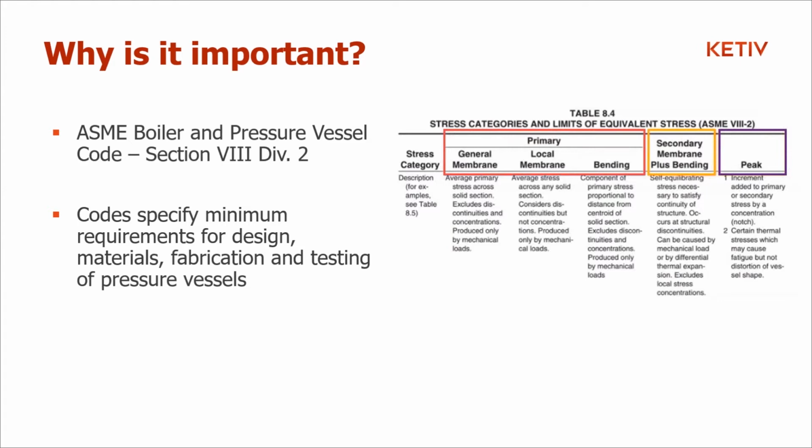You also have sections that are called design by rule or design by formulae. So that's if you're using these rules directly, if you're using hand calcs, as Nigel mentioned, being his favorite part. Oh, yeah. If you're using that, you have separate codes for that. And if you're using FEA, then you have a design by analysis section, which is what we would be interested in.